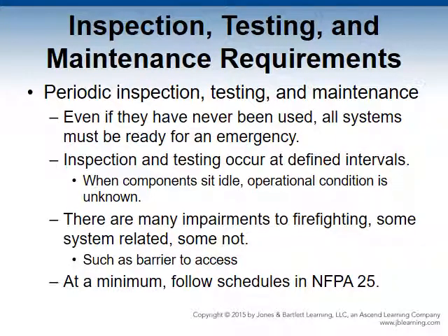Periodic inspections, testing, and maintenance. Even if they have never been operated, all fire protection systems must be ready in case of an emergency. Inspection and testing occurs at defined intervals. When components sit idle, their operational condition is not known. They must be periodically inspected and tested. A simple visual inspection can reveal leaks, corrosion, and damage to critical system components. A water flow test could reveal a closed system or control valve. And hydrostatic testing can determine if components are able to handle the water pressure delivered by the pumper.